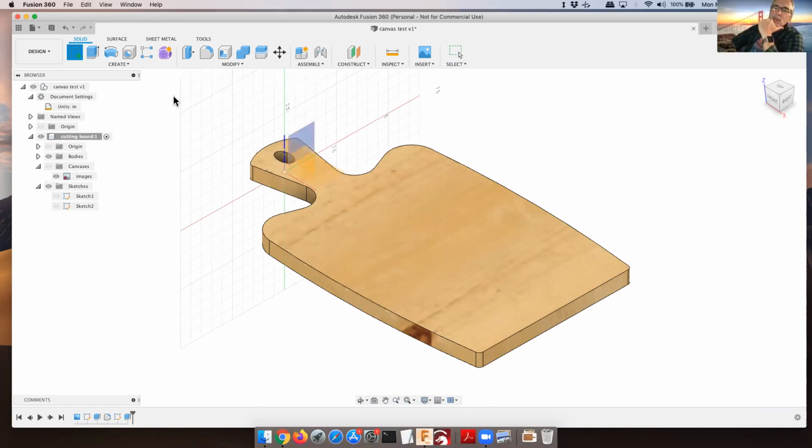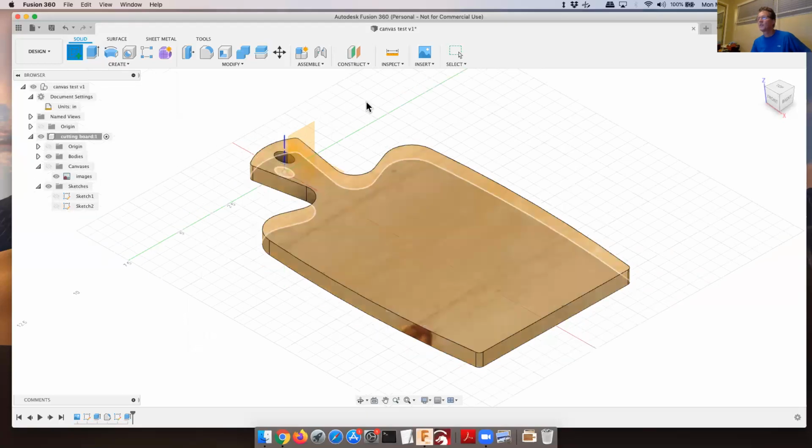Hey, Tim, what you did last week as your final version to create the ball ends of the cracker tray, was that a swept path? I did. The first part was a swept path, a swept cut. And then at the end, I did a revolve cut. Okay, great. So in this case, the whole thing's just going to be one swept cut.